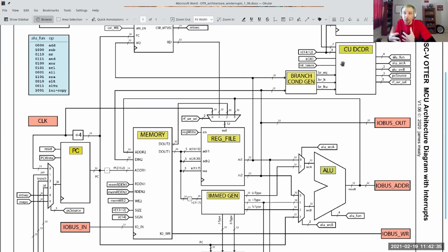But so depending upon how you've done it, right? You could be creating your design with longer chains of stuff as opposed to more stuff in parallel. So we like big muxes. We don't like chains of small muxes.